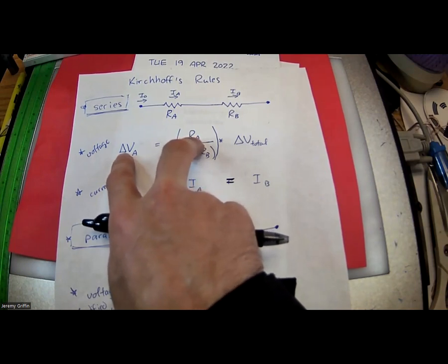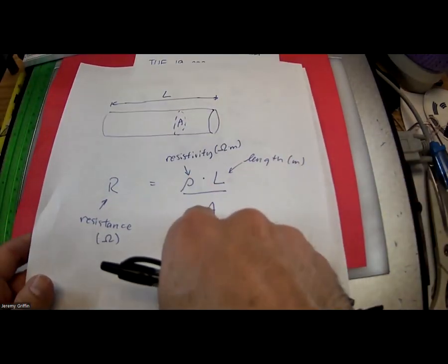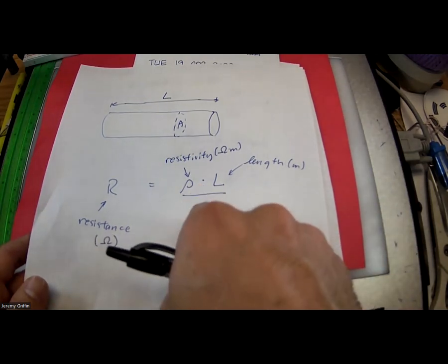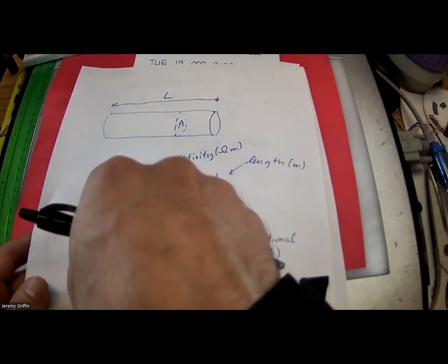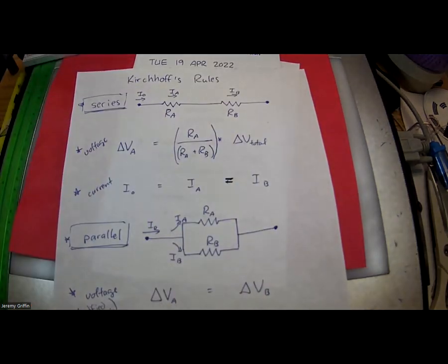But then how do you get a greater resistor in terms of like thick or thin filament? Well, remember, if it's a thick filament, that's a small resistance, therefore a small voltage drop. If it's a thin filament, that would create a great resistance, a huge resistance, and you get a greater voltage drop. Right? Put it all together.